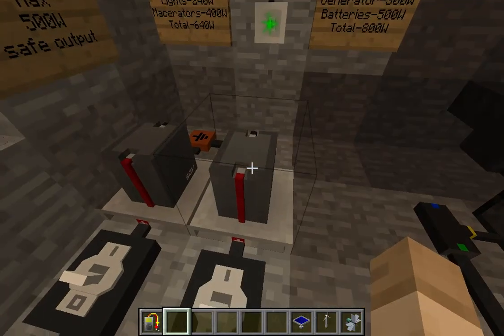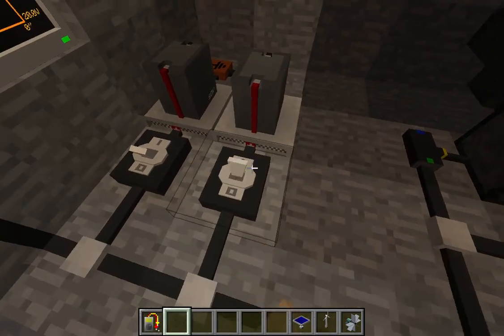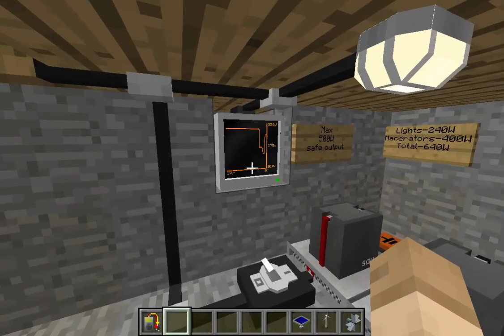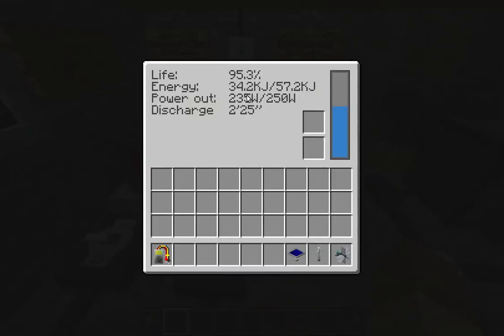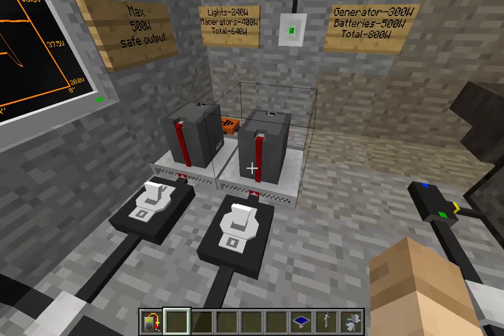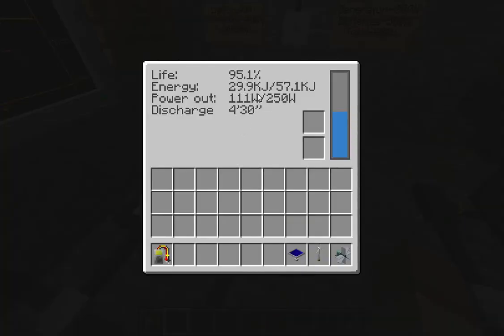Here's where the batteries come in. Turning these guys on produces a boost in power, allowing us to meet that demand. If you'll note though, his power output is close to his max safe power output, and as we learned from tutorial 3, that's going to shorten his battery lifespan significantly. So, despite the fact we're technically currently meeting the power output requirements, it's good to add a second battery. That's going to distribute the load between the two and make sure they last a lot longer.